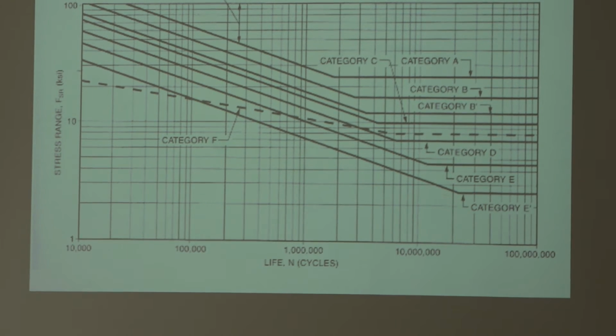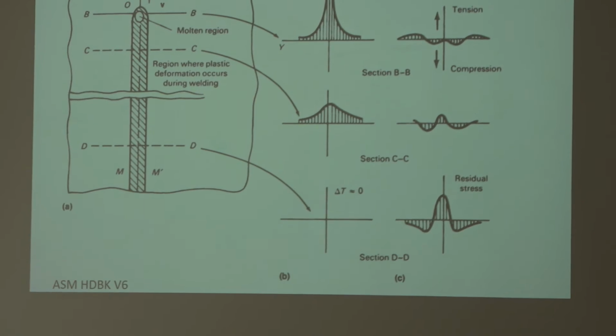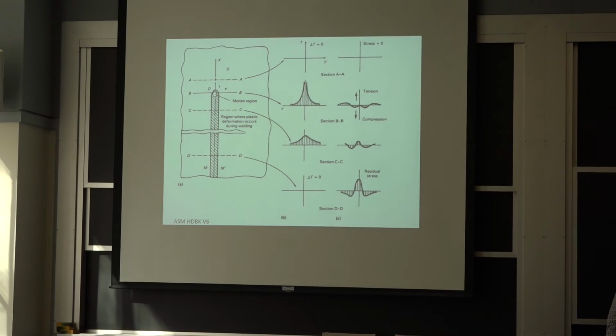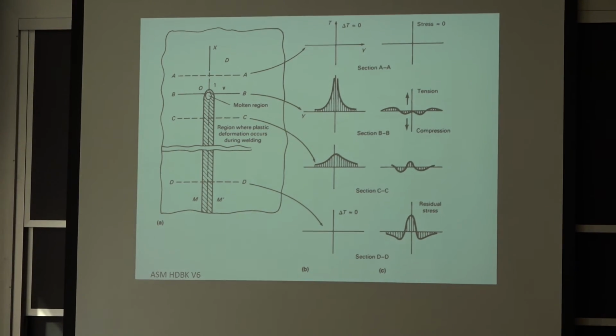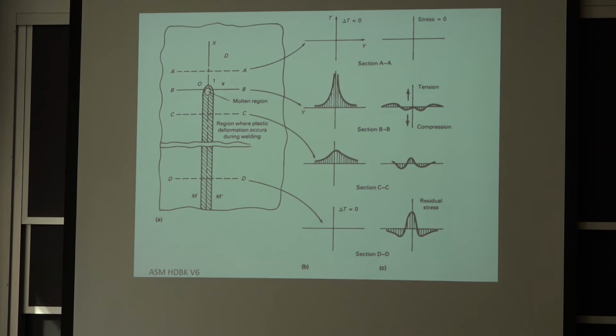So we multiply by 3 just because we change from a fillet weld to a really good quality groove weld. It will have implication if you're building these little cars or carts. There are people that are doing these competitions trying to build a small go-kart. They were somewhat lucky because it was already part of the competition which material to use. So it's weldable and it's got a good combination of characteristics. So essentially, simplify the engineer's life by telling them what would be the highest strength they can use and a specific grade that can be welded without becoming brittle, all that martensite type discussion we had.